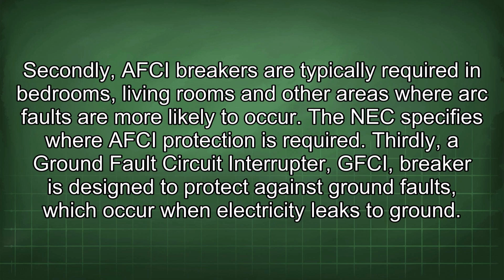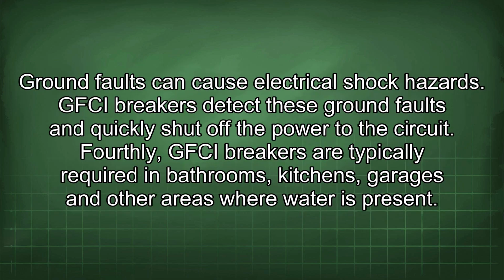Secondly, AFCI breakers are typically required in bedrooms, living rooms and other areas where arc faults are more likely to occur. The NEC specifies where AFCI protection is required. Thirdly, a ground fault circuit interrupter, GFCI, breaker is designed to protect against ground faults, which occur when electricity leaks to ground. Ground faults can cause electrical shock hazards. GFCI breakers detect these ground faults and quickly shut off the power to the circuit.